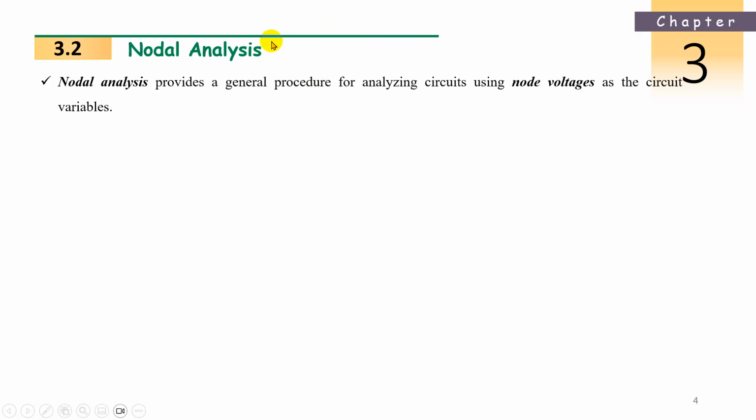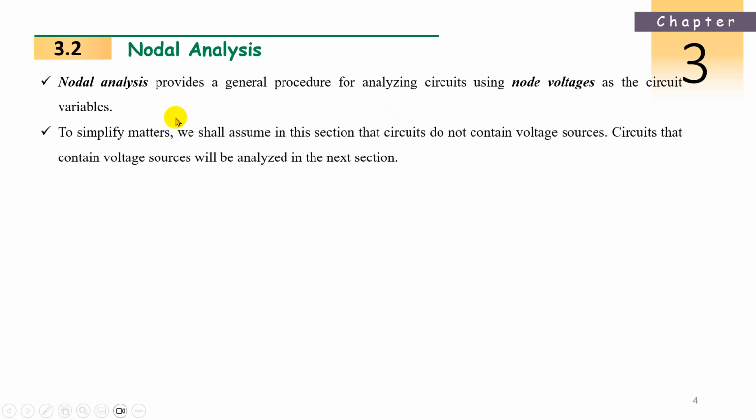So first, for the currents at a particular node, one equation will come. Rearrange that equation with Ohm's law in terms of voltage. That's why we call them node voltages. Now if you take the node voltages as variables, you solve the equations and get the voltages, then resubstitute into the current equation. Then you will get the currents also.